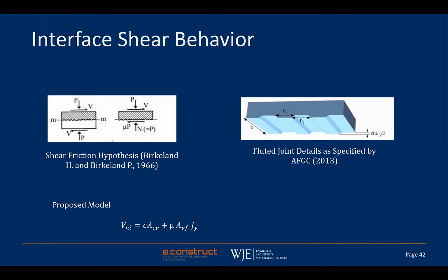We borrowed an idea from abroad. Mostly the French people, but also the Asians and others, are recommending that we use what they call a fluted or corrugated shape on the top of the precast UHPC beam. That can be formed with form liners, and 3 of the precasters tried that successfully, using form liners to create the deformations on the top flange.